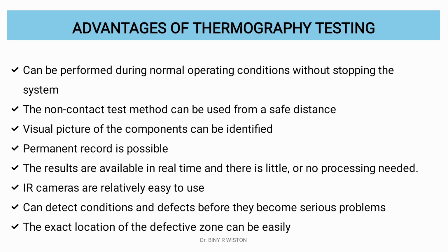The results are available in real time and there is little or no processing needed. IR cameras are relatively easy to use. It can detect conditions of the equipment and defects before they become serious problems. The exact location of the defective zone can be easily identified.